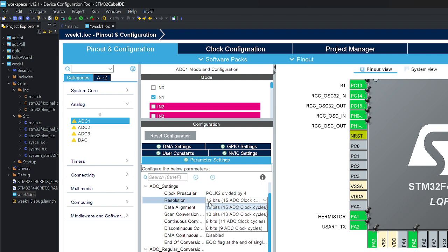There is a structure that is defined when we set up the ADC, and then we do all these selections. It fills in the structure, and there's a HAL ADC init, which takes the things we filled in the structure and sets up the ones and zeros, just like we talked about with the GPIO port. Okay, and so there's that right alignment.